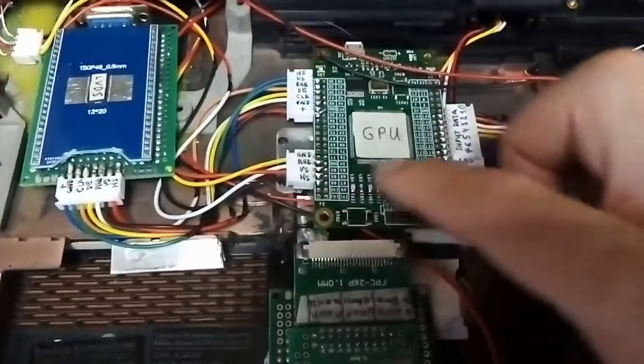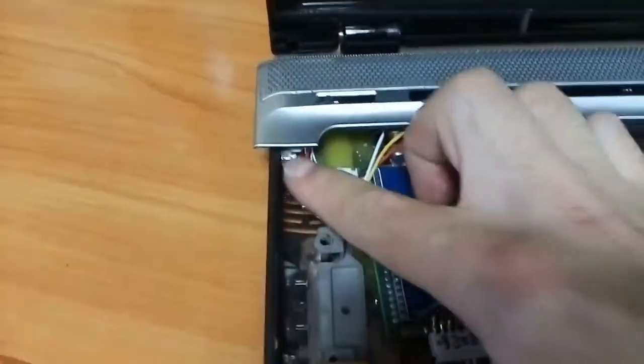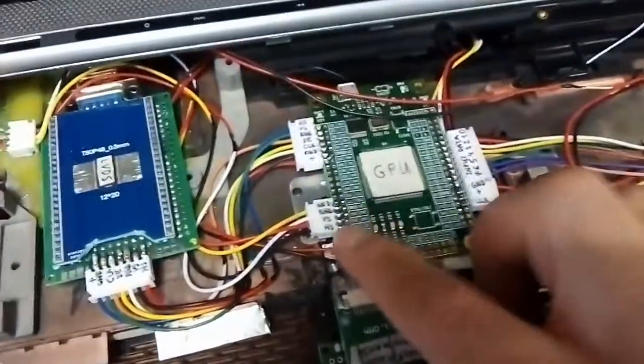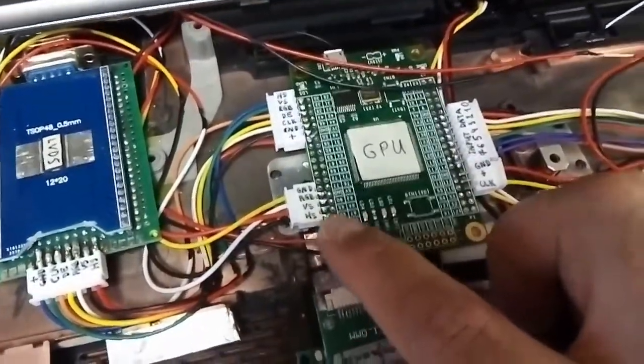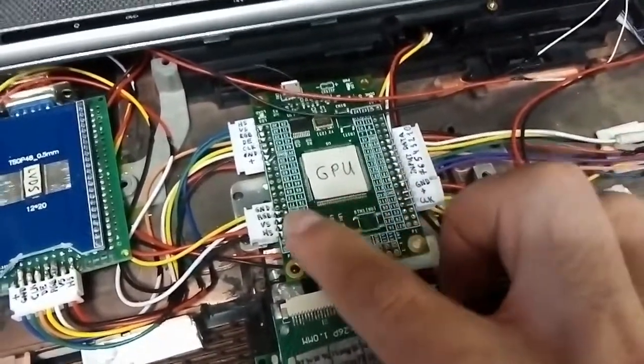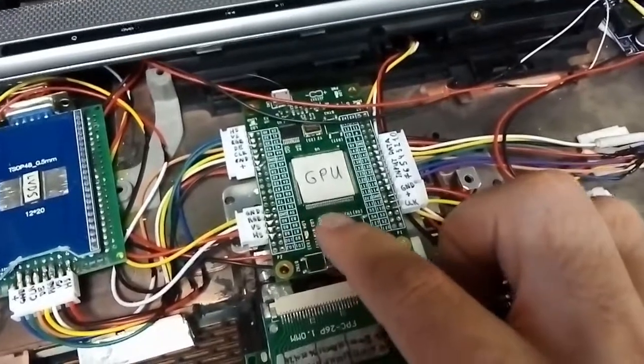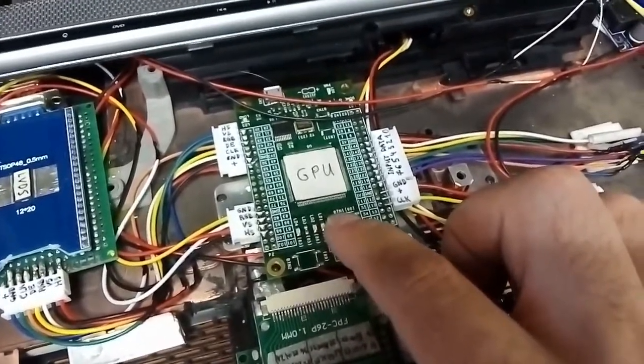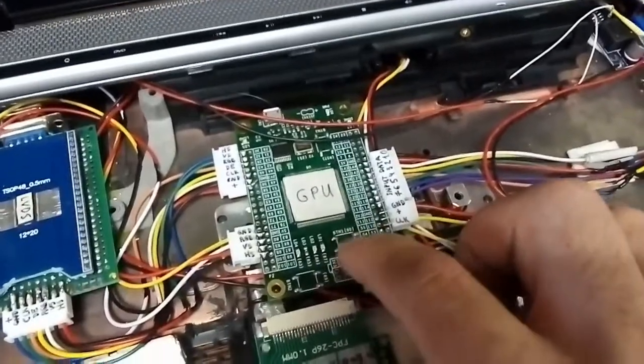And we have also VGA. That's the VGA port. You can connect a monitor directly here, VGA. That's resolution 800 by 600 pixels, and it goes directly to here. That's VGA signal, and it's easier to make VGA, and it makes it itself. That's frequency 40 megahertz, and we have two crystals here.